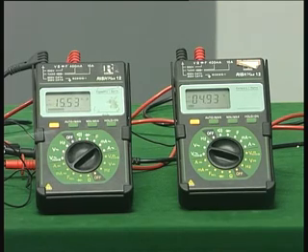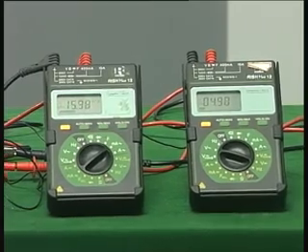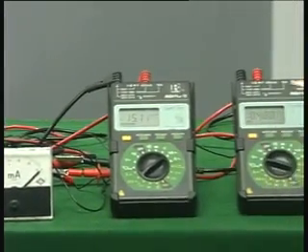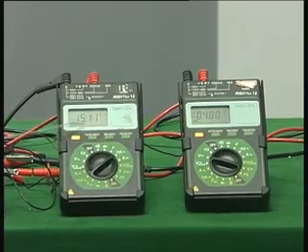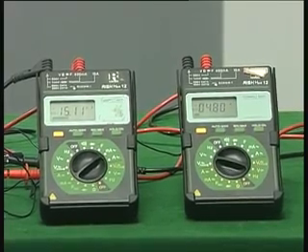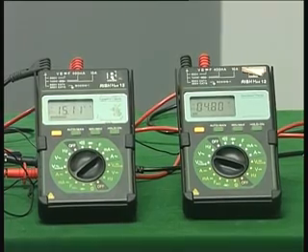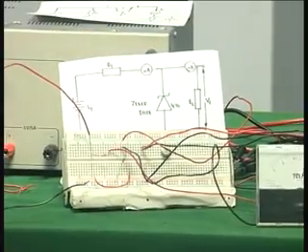Maybe I should have shifted the two multimeters, it does not matter. So you can see if I change the input voltage, the current is changing, but the voltage across the Zener remains a constant 4.9. The load current will also remain constant, because that is dictated only by the load resistor that I have connected. So 4.9 divided by this, 330 ohms I think, is around 15 milliamperes.